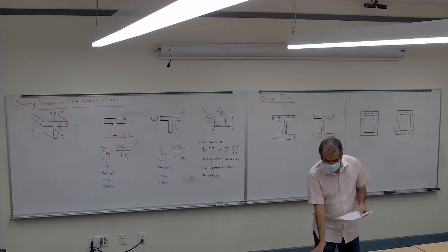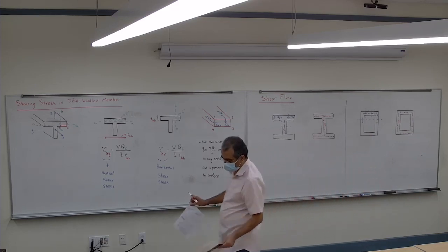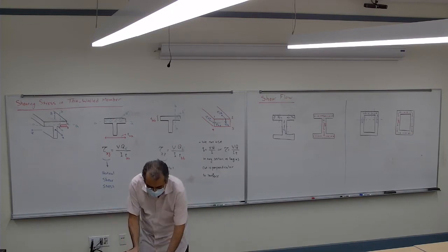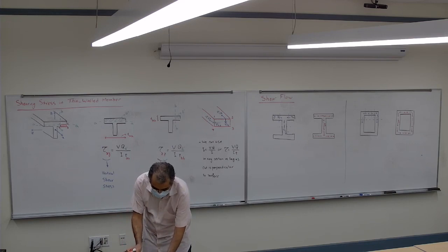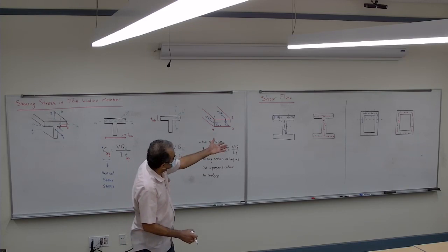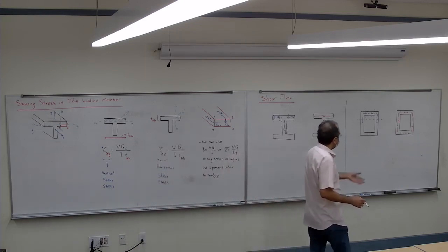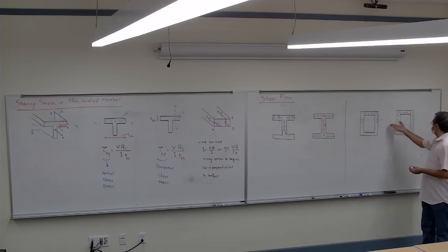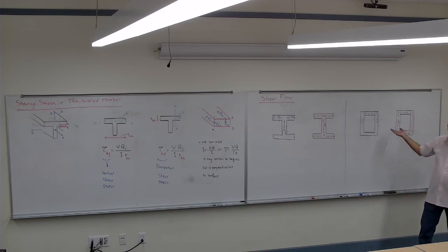So basically it shows you how the shear stress or the force in the cross section will change across the section. Visually you can see that, and if you're given that, you can look at it and say, okay, where the shear is 0 and where it becomes maximum. And you know that it's always maximum when you are close to the neutral axis.